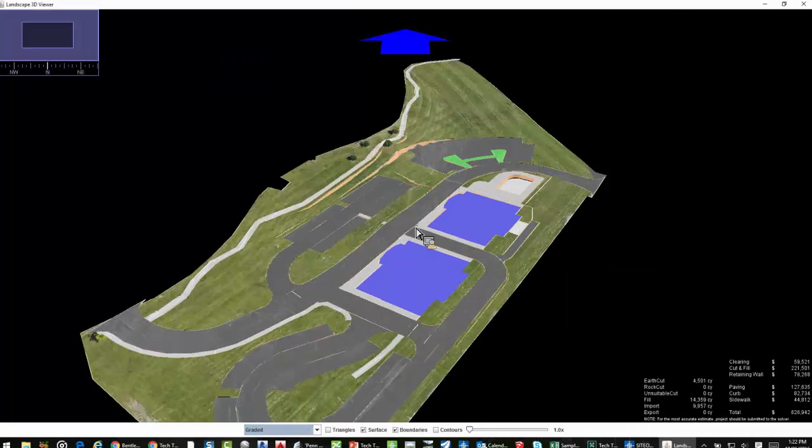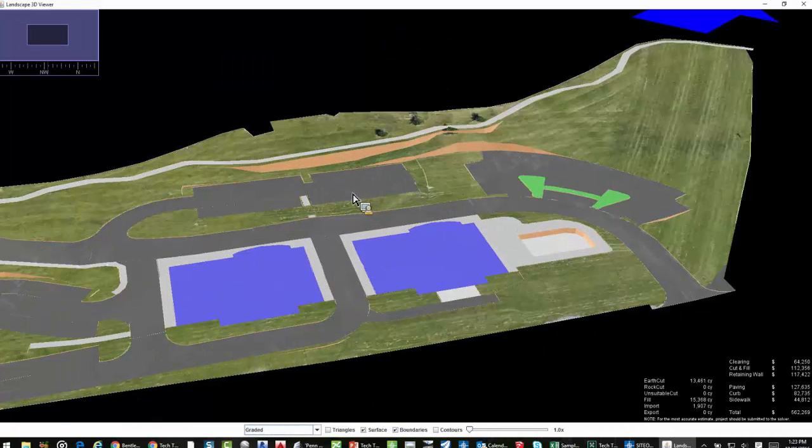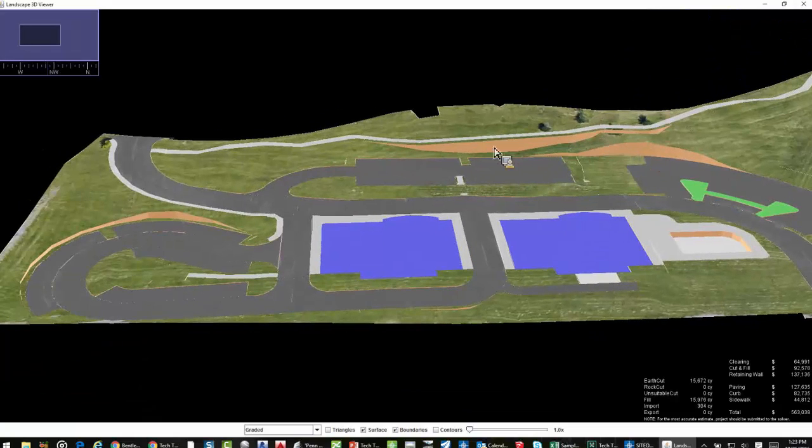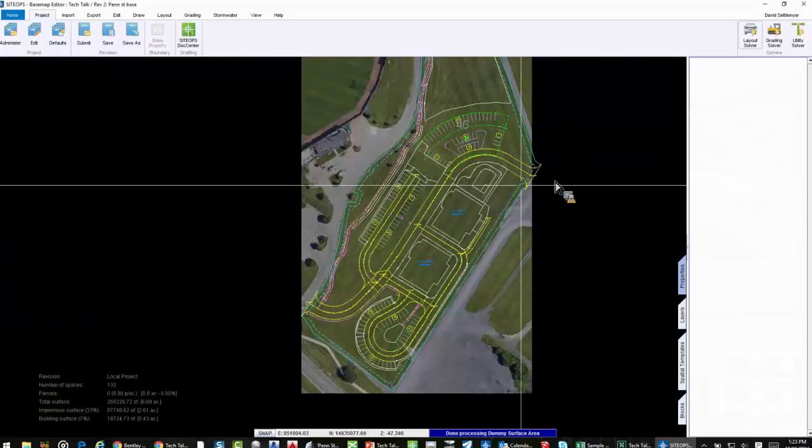we're going to let SITEOPS grade, and now you can see walls. All of a sudden that little wall became bigger. That one along the sidewalk is bigger. Now again, we're going to put rails up there. It becomes a bigger issue, but we've got to make the site work, or who cares where the sidewalk is, right? We've got to beat the fundamentals. The same around that lower arch parking lot. We've got to be able to solve that problem. And you notice the grading issue goes away.